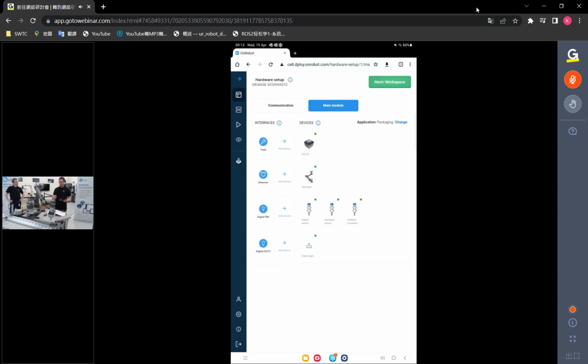The output right now is specified as green light. That is because it's a green diode that is connected down here. This can be used for events in the applications. So if there's something happening in the application, if we run out of in-feed trays, if the part is dropped, then we can use it as a signal for an operator to intervene with the machinery. So this is the first step, defining the parts, defining the setup, and that's it.